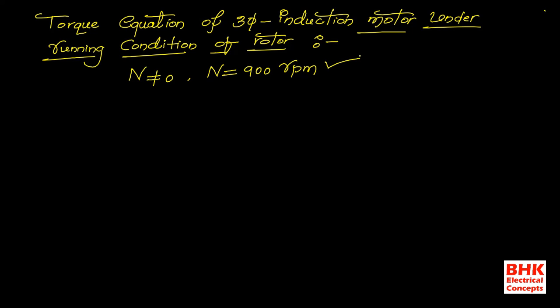Clear? And you know that the synchronous speed of the rotating magnetic field is N suffix S. The synchronous speed of a rotating magnetic field is always not equal to 0, and its value always depends upon the supplied frequency as well as the number of poles on the stator.